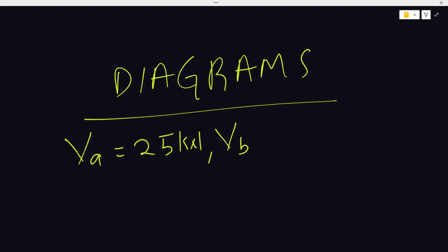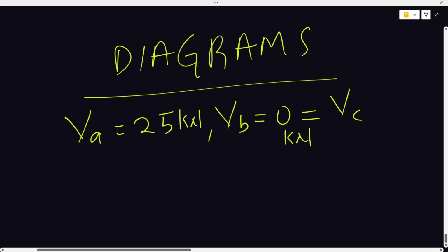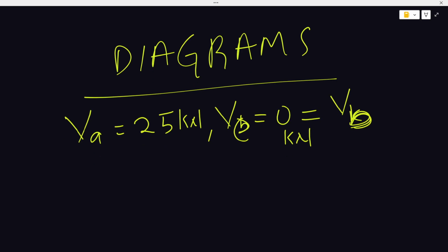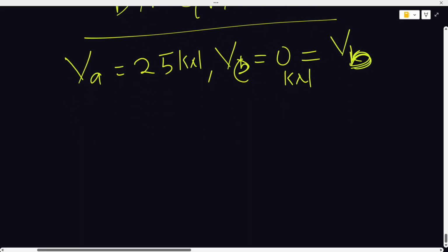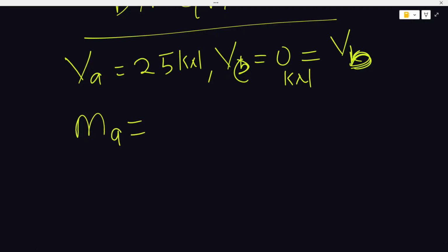Our shear force at B was 0, which is the same as the shear force at C. Yes, which is the same as the shear force at B for member AB. And similarly for member AB, our bending moment at A was minus 430 kilonewton meter.